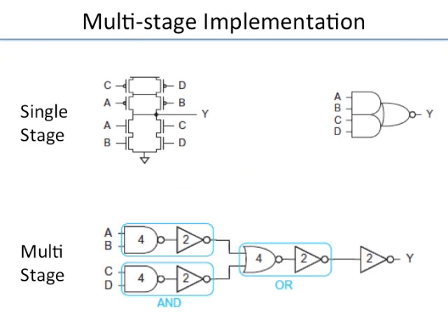So then the question is, why does no one build one? You could take a whole combinational circuit and build it into one humongous gate, right? People don't do that. There is a point at which you say, look, enough complexity in a single gate, now I really need to cascade gates. There is a point at which a single gate becomes complex and slow, and it's better to have multiple gates.